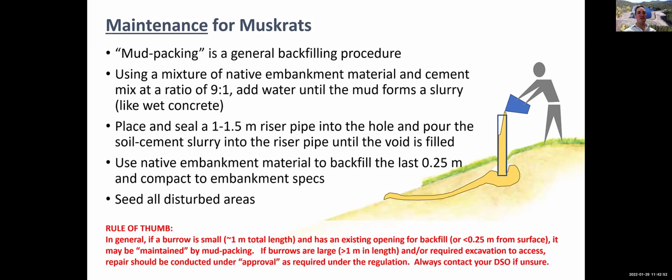And they say too, you don't really want this mud pack on the top. So where you have access and you can get some good compaction, fill it in with the embankment material, preferably moisture controlled, and get some good compaction on it. And seed all disturbed areas. And that goes back to that other question, was the area seeded?